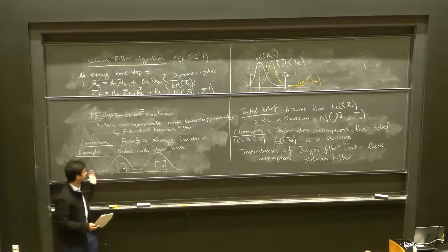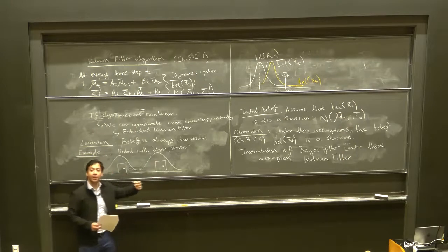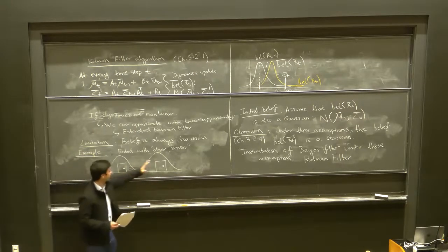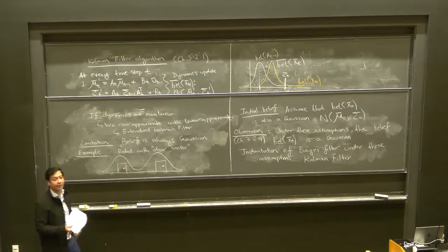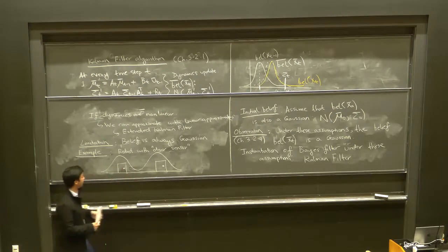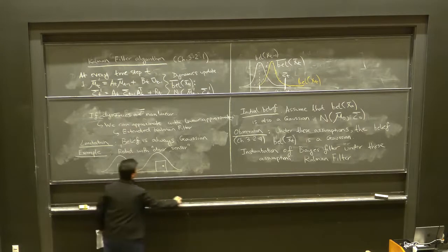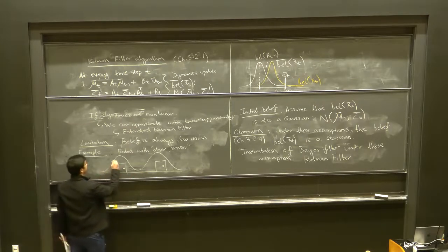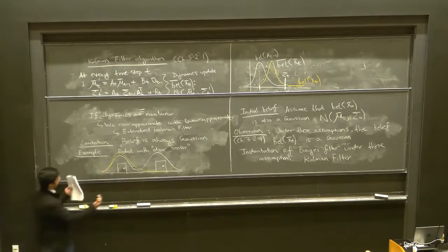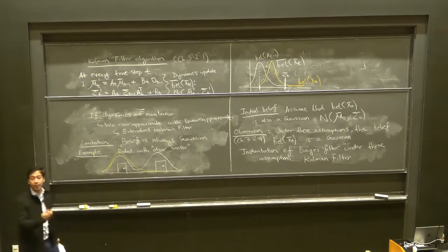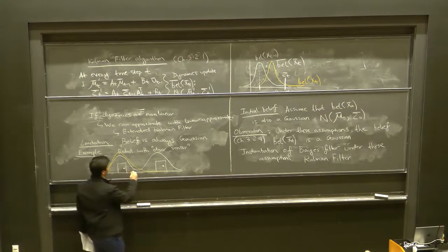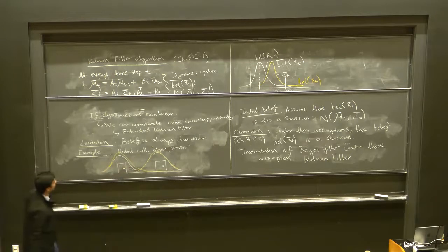If you have a Kalman filter, then you're fundamentally committing to Gaussian beliefs. And this kind of bimodal belief, or multimodal belief in general, we cannot capture well. We can capture it clumsily, but not really well with a Gaussian. There are a couple of options. One option is to place a Gaussian whose mean is at one of these doors, though this is not to scale. But that's not really satisfactory because we could equally well have been close to the other door. We could pick the other door, but that has the same problem. Or we could just split the difference.